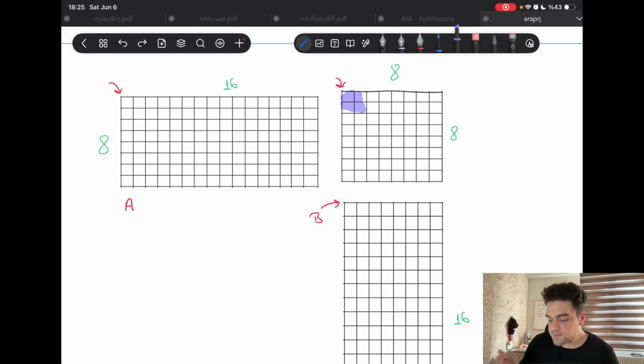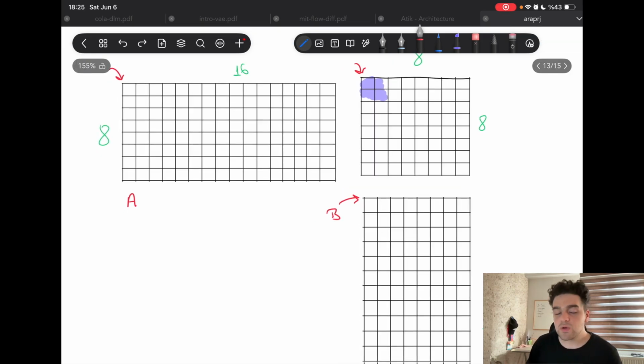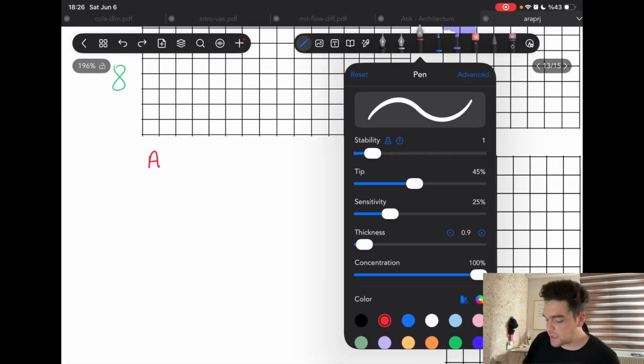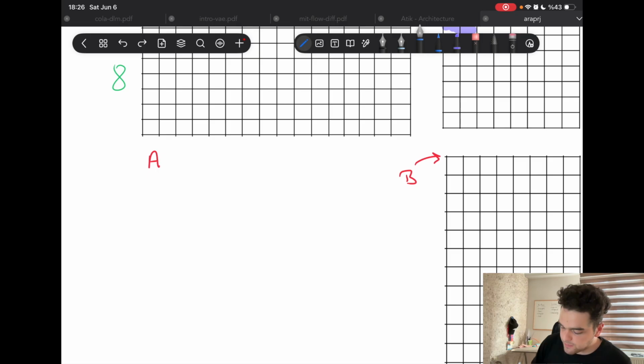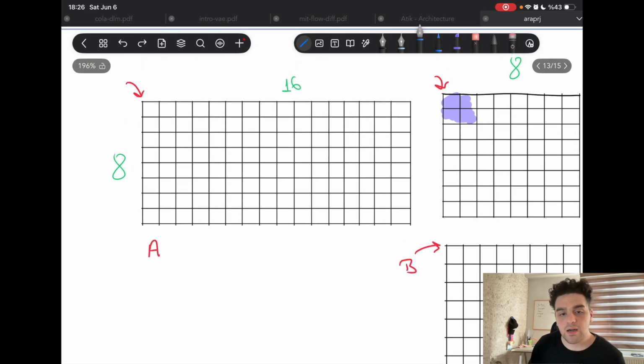So to solve this problem also, we are going to use SRAM banks, and we will store part of the huge matrix in these SRAMs, and then retrieve what we need from the SRAMs. This way we can reduce the memory overhead, but at the same time it is more expensive. However, it is much faster. So we need some kind of SRAM banks that will store part of the matrix.